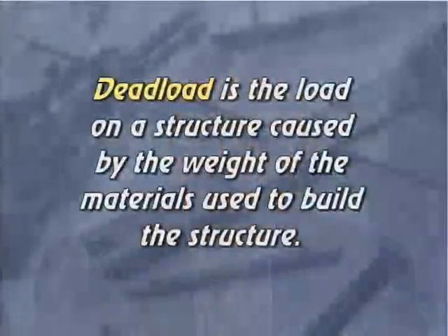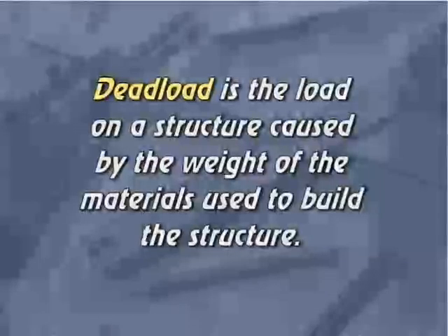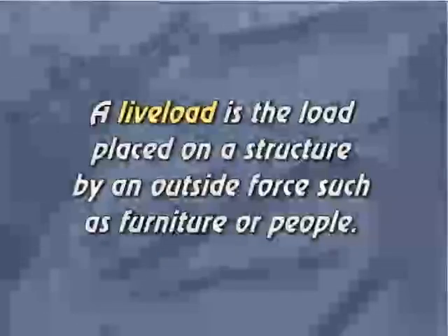Framing loads. We talk about a live load and a dead load, and it simply comes down to this. Once you have finished there as a carpenter and nothing is in the house, the weight on the structure is called dead load. So that would be studs, sheathing, beams, and so on. Once you begin to load that house with items from furniture to carpet to people, that's considered live load.